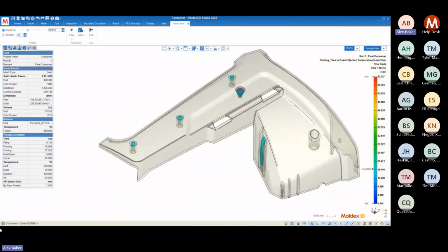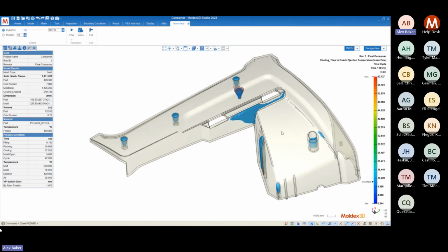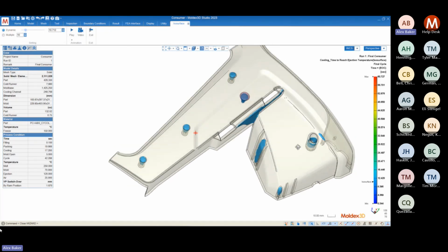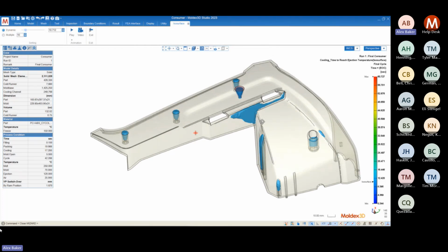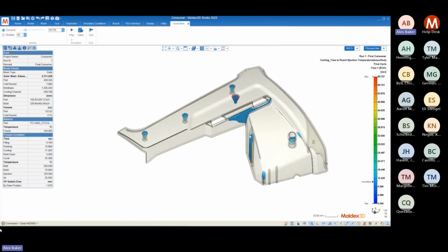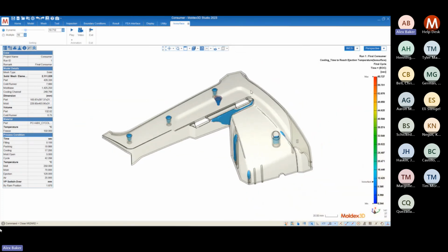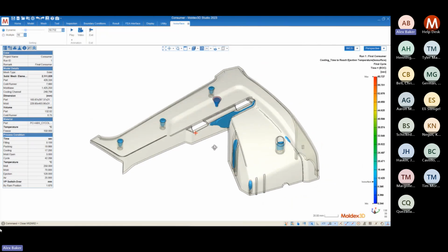We can just let it cool outside of the mold. And as a result, we can save a little bit on our cycle time. All right, so maybe I could go down to something like 10 seconds instead of 17 seconds. And this is where simulation can really benefit you, allowing you to see where the hotspots are, how long it takes for each of these features to cool down, and ultimately where you can save time and money in your production cycle.